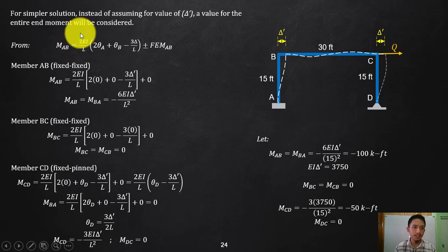Please pay attention to this. How do we get that end moment? Isn't it that we do not have these member loads? Of course, we only have that. This will be considered as a joint load, but in the first place, we do not know that one. That is what we are trying to get, the ratio to your force R. So you cannot make use of your fixed end moment formulas. So the end moment is actually from your slope deflection equations.